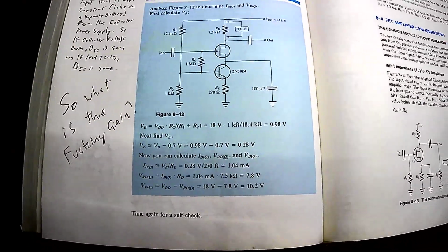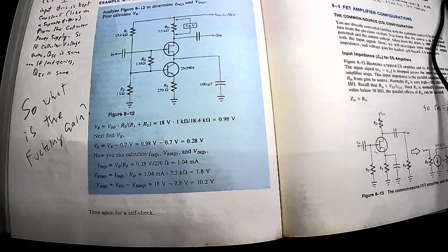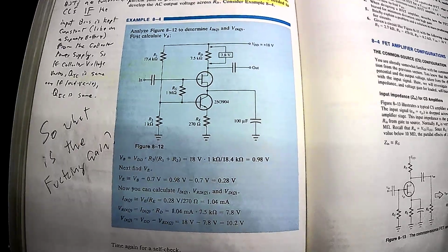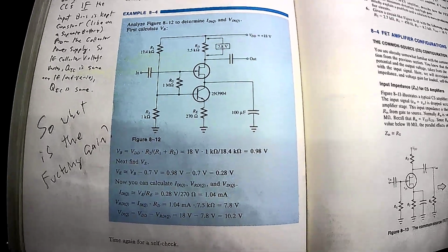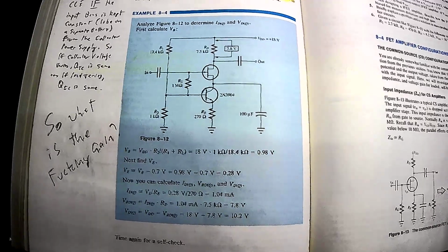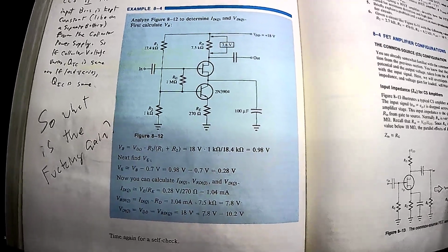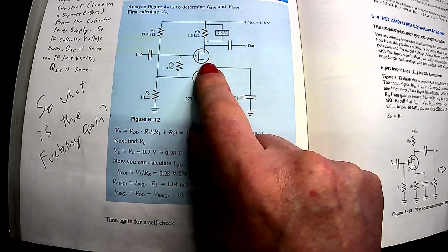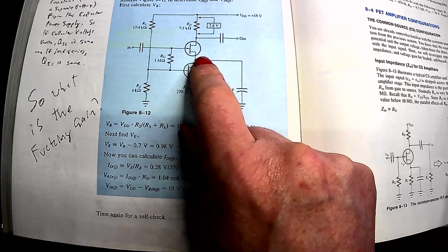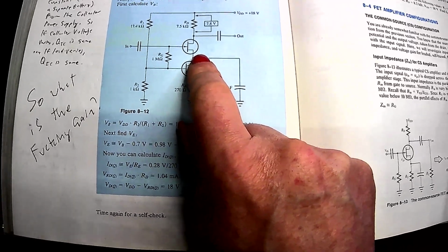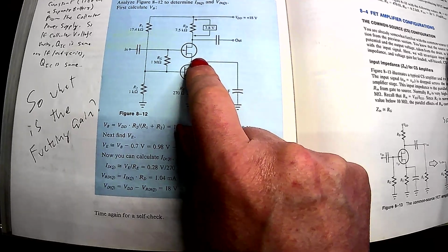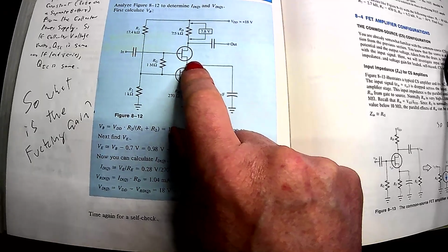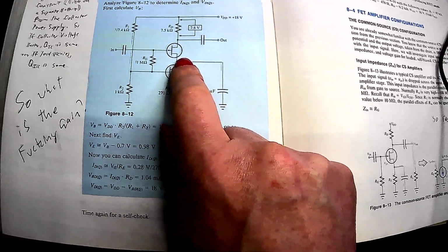But at any rate, for the sake of completeness, I thought it'd be worthwhile to mention that. And if you go to the ESP, Elliott Sound Products website and read his JFET sections, he has a lot of circuits like this, like constant current sources, to give you gain amplification. Because that's one of the problems with a JFET, generally speaking: there's not enough gain to work with. They're pretty low gain devices. With a bipolar transistor, you usually have betas of 100 to 250 or so, just with a plain Jane transistor, and that's a lot of gain to work with.